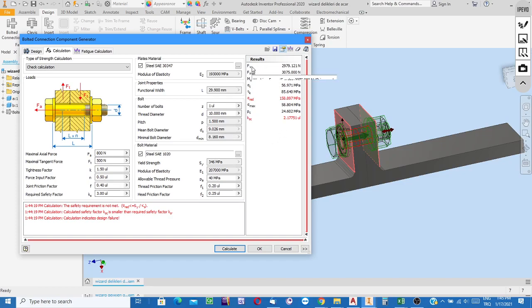And here, during the screwing stage, the maximum axial force value is in this order, 3000 newtons. The preset force, after removing the driving torque, is the force that grips, near to 3000 newtons. And M sub U is the screwing torque, the necessary tightening moment.